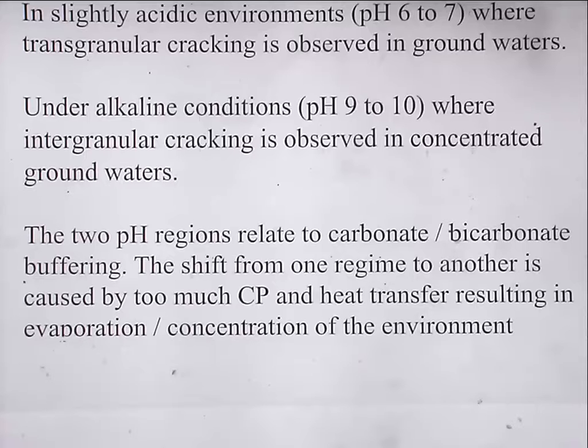So the intergranular attack in the alkaline conditions, that had been known for quite a long time, since the mid-1960s. And people thought they'd got a handle on that and understood it. It was the transgranular cracking that started appearing in what they call the near-neutral solutions in the 1980s and 90s that rather scared the people involved in oil transportation.